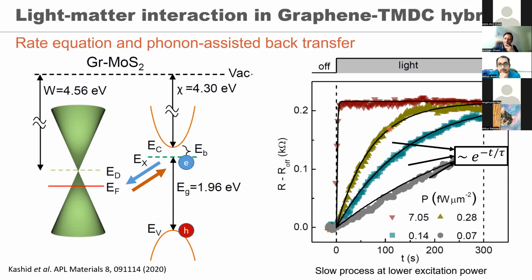Thanks. And to begin with, your chalcogen layer, is it also doped, or what's the doping state? We have done both. The chalcogen layers are not doped intentionally. MoS2 usually comes with a very strong N doping by itself. But there are tungsten disulfide, diselenide, etc., which are relatively undoped. We find better results with the undoped ones, for example, the tungsten disulfide or diselenide. But overall behavior is the same. I see. Okay, and one last question.